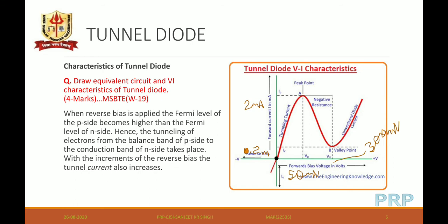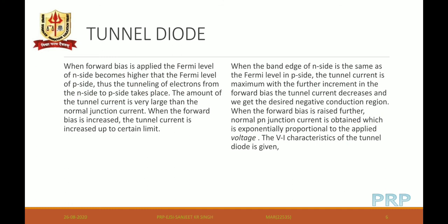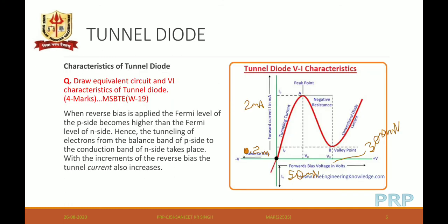So this dynamic resistance characteristic is of very much importance, and again by increasing the DC bias voltage further, we can increase the conventional diode current. So this process can be repeated and can be used for microwave oscillation production or for generation of microwave signal. The given VI characteristic is that of germanium.